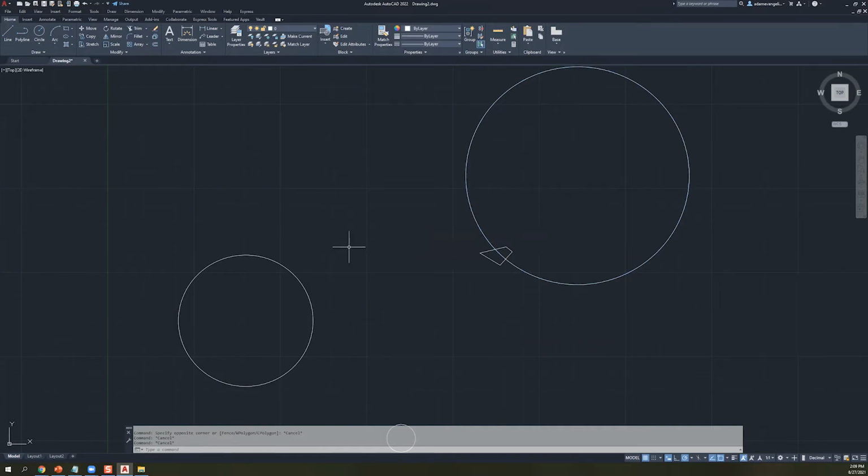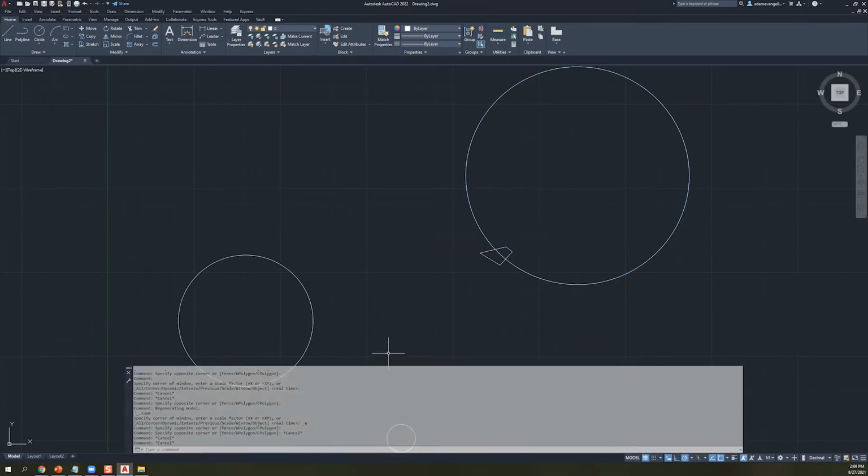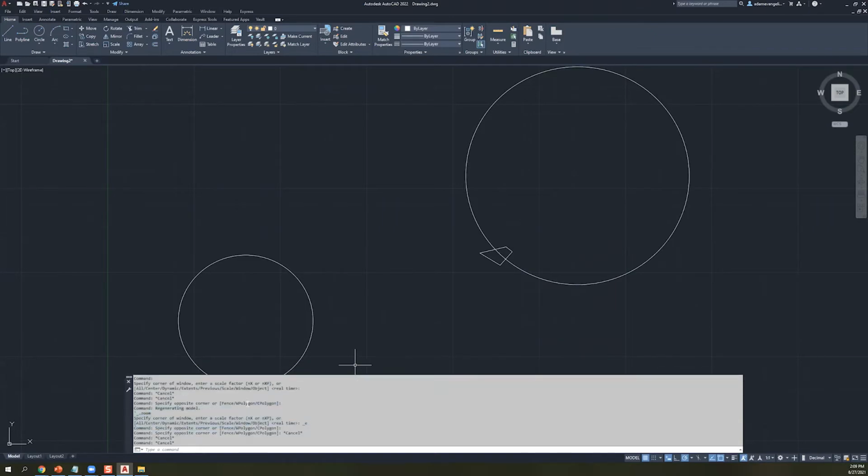One of the other things you might be seeing as I go about using all of these different commands is that my command line ends up updating as well. This big bit on the bottom is all about the command line, and this harkens back to AutoCAD's original inception. One of the more unique things about the application, I think, is that it has an active command line. It's really similar to old DOS operating systems or just command line operations. You have a command line where you can input commands as you want. You don't necessarily need to know how to program to work with this, but you can see there's already a record of different things going on as you press buttons and hit keys.